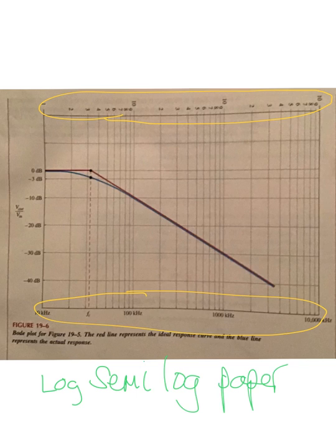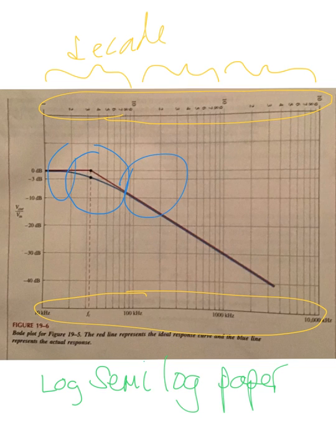You can assign anything you want. What they're doing here is going up in decades. See, that's a decade, that's a decade, that's a decade. And usually when you're talking about decades of frequency, not a lot changes sometimes between decades. So in an attempt to compress your circuit, to give you a chance to see this critical frequency and a little bit around it on both sides, they compress the frequency scale down here in blue check marks.